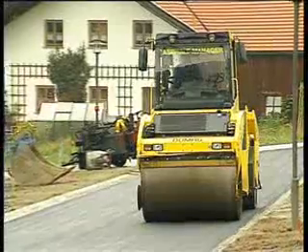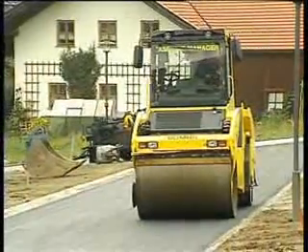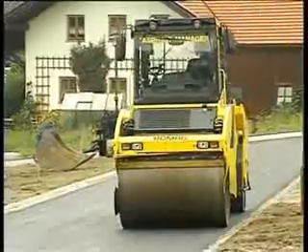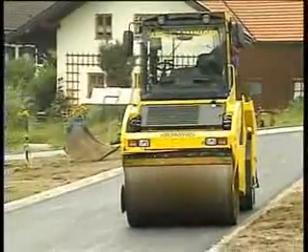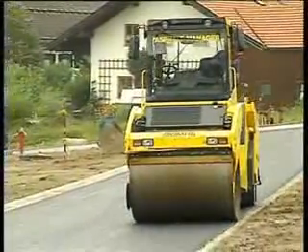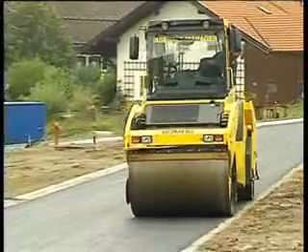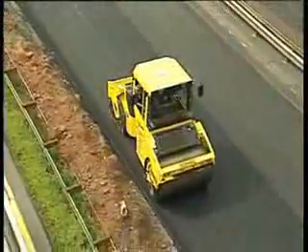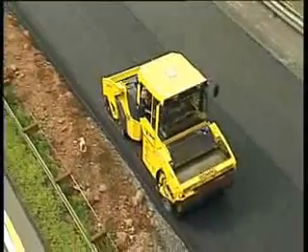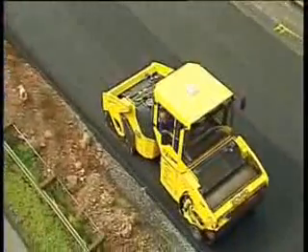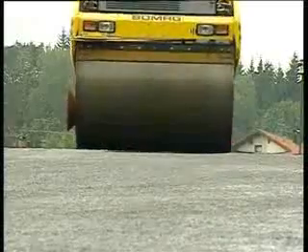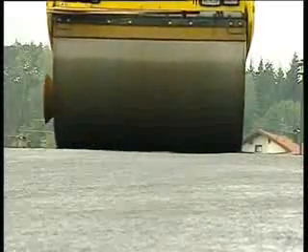Contractors focus on 2 things: the cost of compaction and its quality. So rollers need to complete compaction using the fewest number of passes possible. They should also be versatile and be able to handle a variety of compaction jobs easily, from wearing courses to base course layers. Important quality requirements such as evenness and texture must also be met.